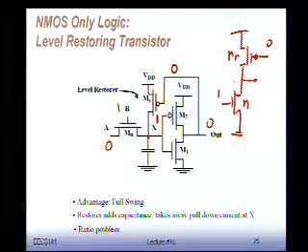It's a pseudo NMOS inverter. And remember about the VOL? Depending upon the ratio of those transistors, the VOL will be positioned at a certain place. If the VOL is larger than the switching threshold of the inverter that follows, you're never going to switch the gate. That gate is stuck. There's no way in the world, whatever I apply at the input, I can pull low and keep on pulling, it's not going to go anywhere. The output is going to stay low. I'm stuck.